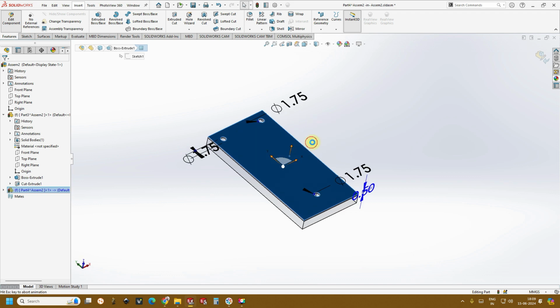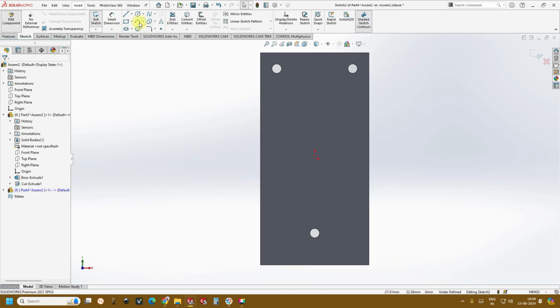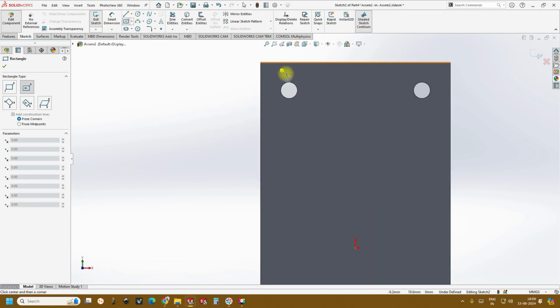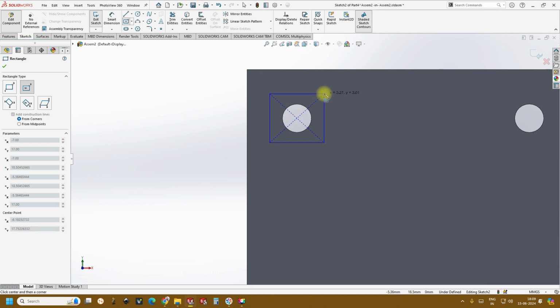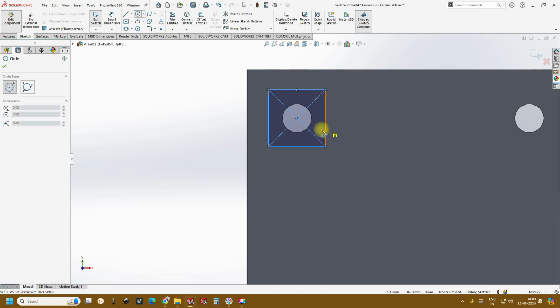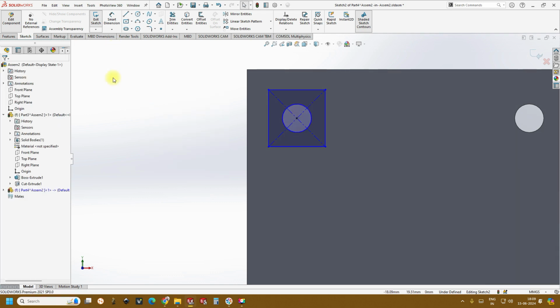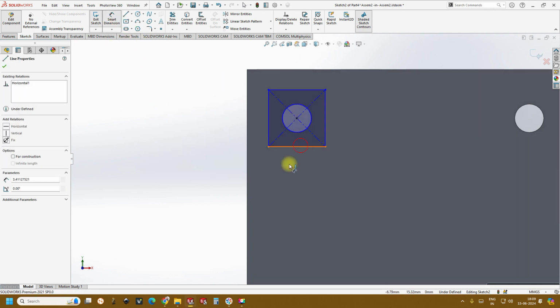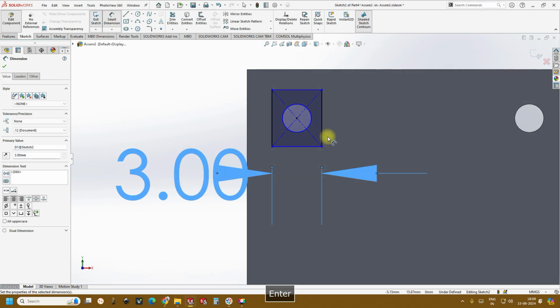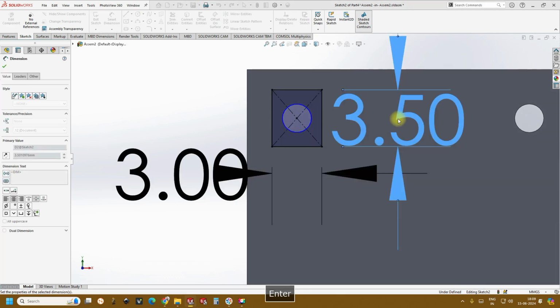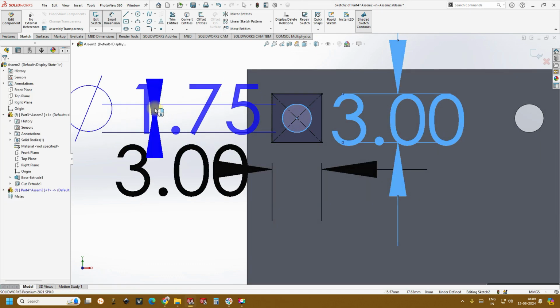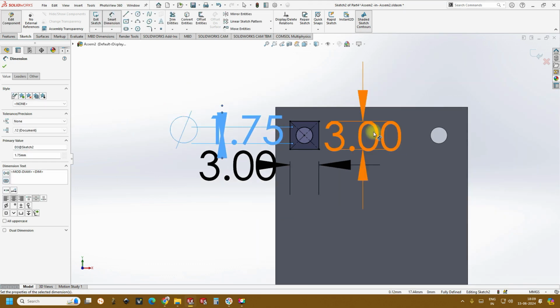And click on this, create another sketch, and same here, let's create a center rectangle, another inlet, 3 mm cross 3 mm. So these are the pillars to give support to the inlet and outlet.